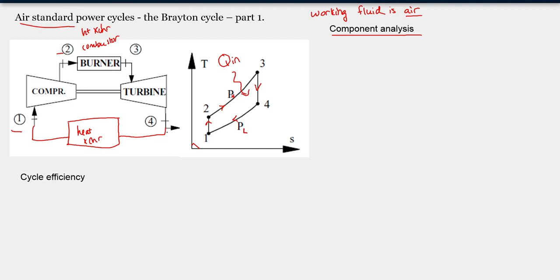And hopefully you see what I mean by if we feed air into the system and then we exhaust it out the stacks, we don't really have a physical heat exchanger in this cycle, right? Imagine your jet engine on an airplane. You essentially have the inlet, which then compresses the air. You have the combustor, which adds fuel, and we burn the air. And then you have the expansion out the back of the jet engine, but there's no heat exchanger to reject heat, right? That heat just gets dumped into the environment. That's important because we're going to use that information very shortly. So again, this just allows us to complete the cycle analysis.